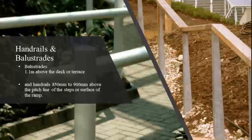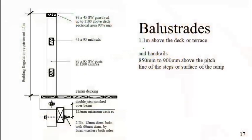A balustrade should be 1.1 meters high for protecting the edge of a balcony. The illustration on the screen shows a typical section of a timber balcony balustrade. The top guardrail or balustrade must be strong enough not to collapse if several people were to collide with it simultaneously.